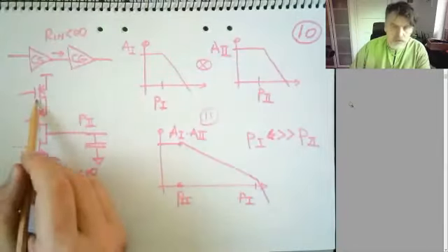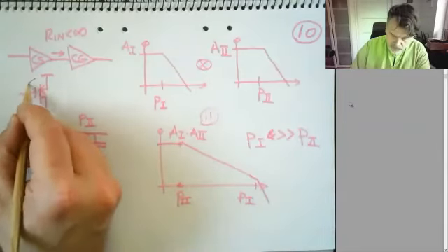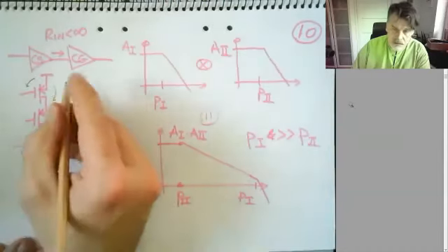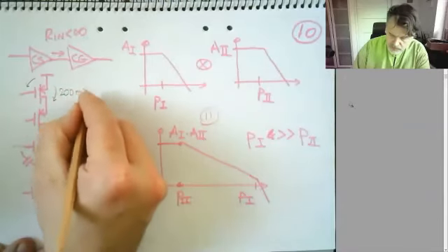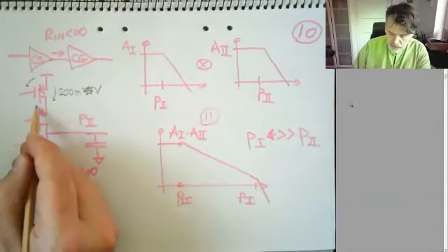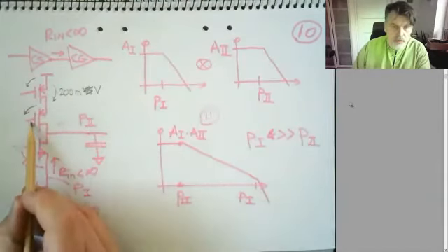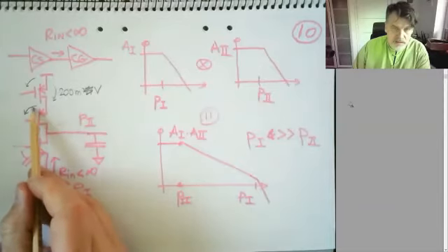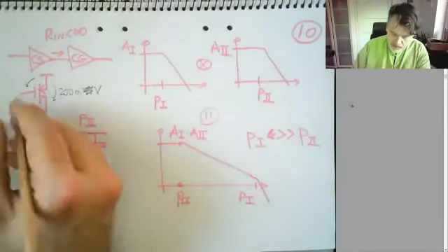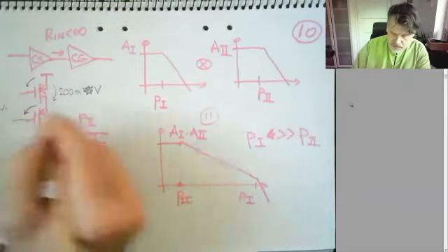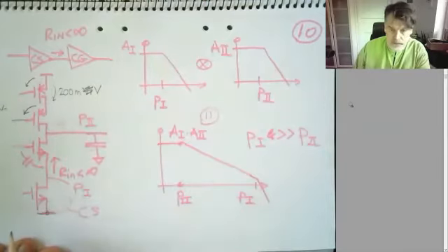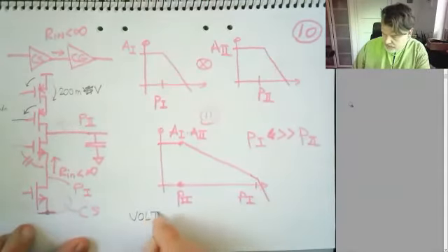So if I want to turn on this transistor, I know that I have to have at least a threshold voltage here, and that will give me a certain voltage here. I don't know, let us invent 200 millivolts for the sake of argument. And then I also know that this voltage, in order to turn on that transistor, has to be the VT, but also an additional 200 millivolts here. So I have like VT, this voltage here has to eat up more voltage range, etc., etc. So voltage headroom is suffering.